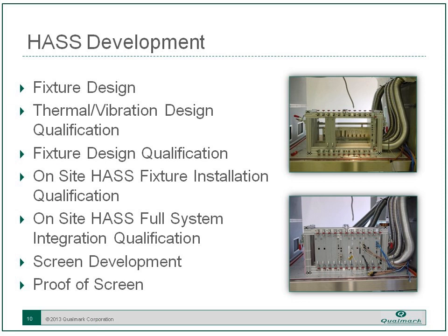The whole process of the development of the HASS screen will often start out with the fixture design, where you're figuring out the way to get many products fixtured into a chamber. For HALT fixturing, it's pretty easy. You're just doing 1 or 2, sometimes 4 units, and it's not really critical that it be exactly reproducible, and you can enjoy the privilege of damaging product if you see fit.